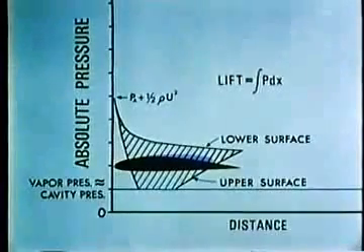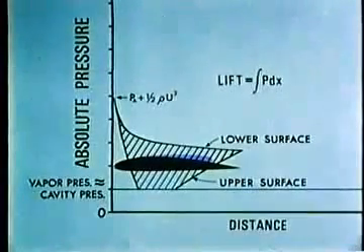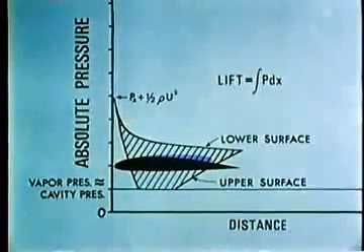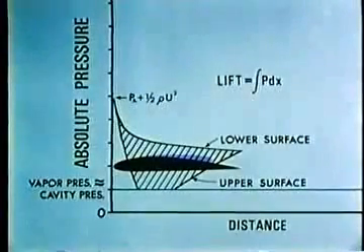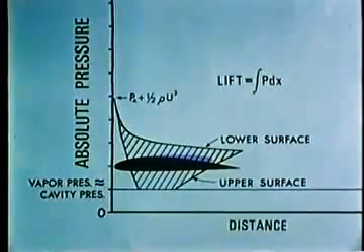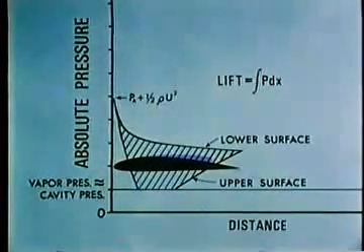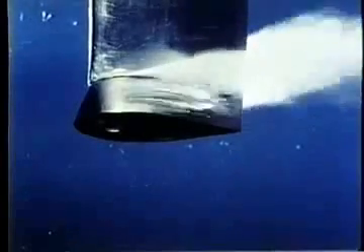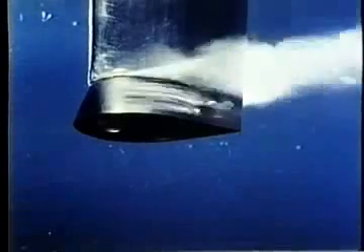Since the pressure on the lower surface does decrease, the lift drops. Actually, as cavitation develops, the shape of the pressure distribution changes somewhat. The resultant pressure distribution is such as to cause an increase in drag. Thus, hydrofoils, and for the same reasons, many hydraulic machines which are designed for efficient subcavitating operation lose efficiency when cavitating.